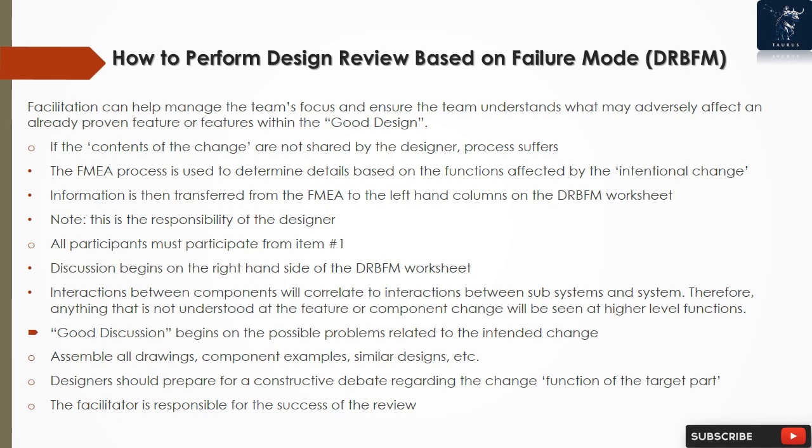The FMEA process is used to determine details based on the functions affected by the intentional change. Information is then transferred from the FMEA to the left-hand columns on the DRBFM worksheet. Note, this is the responsibility of the designer. All participants must participate from item number 1.